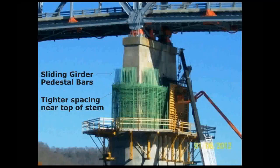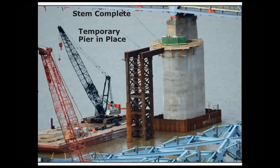So you can see here the rebar for the upper portion of the pier stem. This is the portion that carries the loads from the sliding girder, which supports the truss in its temporary position. And the loads in this part of the cap are extremely high because of all that force from the truss. You can see tight reinforcement here at the top of the stem, and then these vertical bars sticking up are going to go to the sliding girder pedestal, which is the concrete pedestal that supports the truss. And here you can see the completed pier stem.